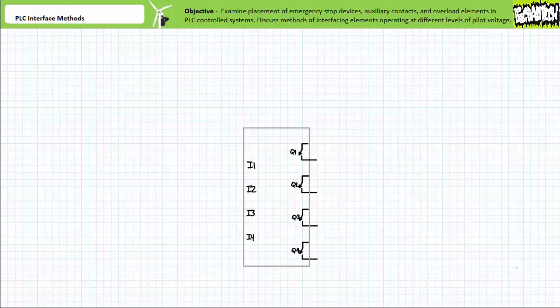When you surrender authority to a soulless and easily manipulated inanimate object, things can and will go wrong. The point being that pilot commands intended to initiate immediate specific action in emergency conditions should never originate from a PLC, but rather be physically hardwired into a system such that they can and will override a PLC.